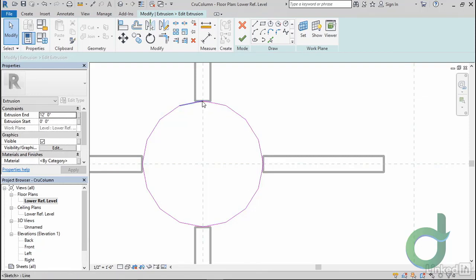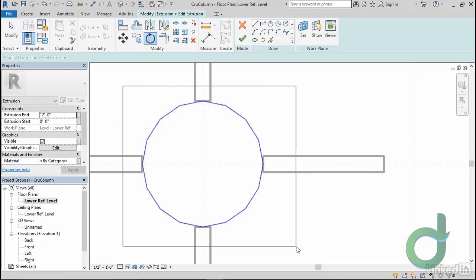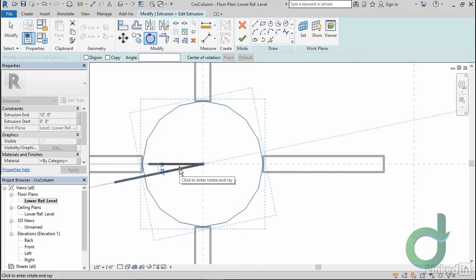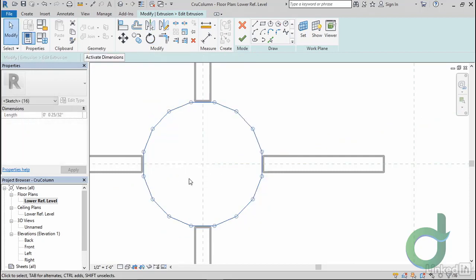We can see that I've got each of these pieces of steel actually hitting a point, and so I'm going to get a little gap here, which again will give me a lighting goof, or a shadow artifact, or light bleed, or something similar. What I'll do is to pick this object and rotate it, starting at 0 and rotating around until those go flat. Here's 11.25 degrees. And now I've got a flat side, pretty close in size to that steel, facing out to the steel. This way, two things I've got that'll really help.